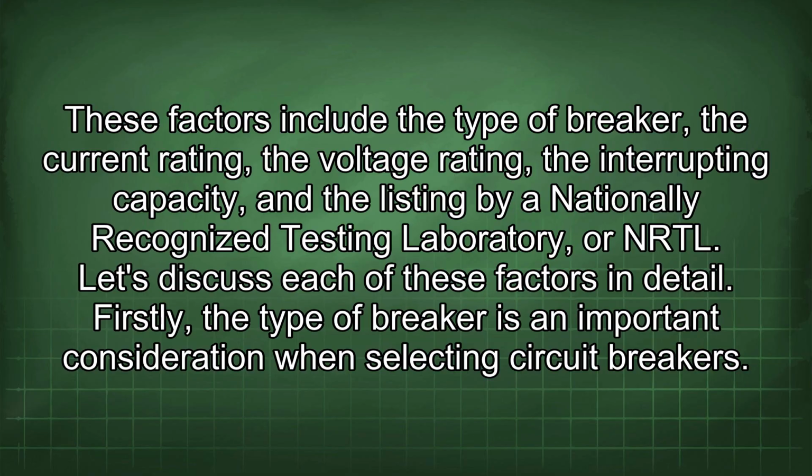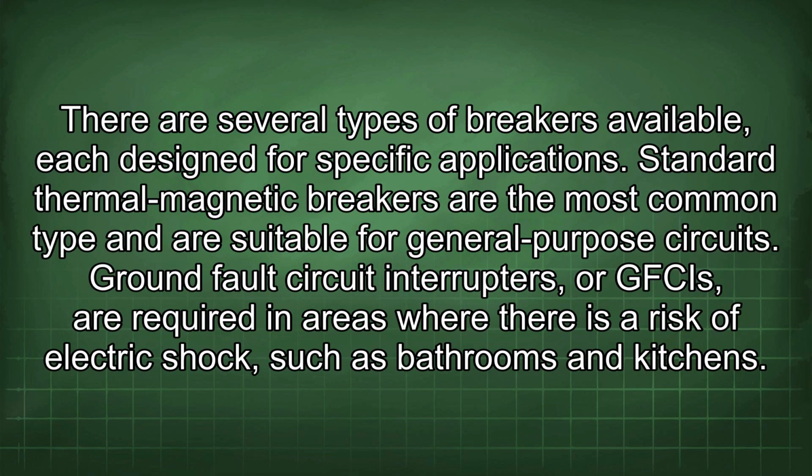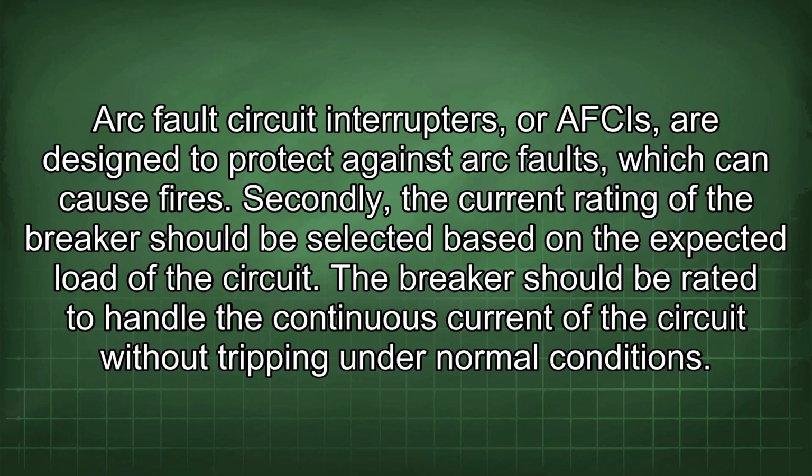Firstly, the type of breaker is an important consideration when selecting circuit breakers. There are several types of breakers available, each designed for specific applications. Standard thermal-magnetic breakers are the most common type and are suitable for general-purpose circuits. Ground-fault circuit interrupters, or GFCIs, are required in areas where there is a risk of electric shock, such as bathrooms and kitchens. Arc-fault circuit interrupters, or AFCIs, are designed to protect against arc faults, which can cause fires.